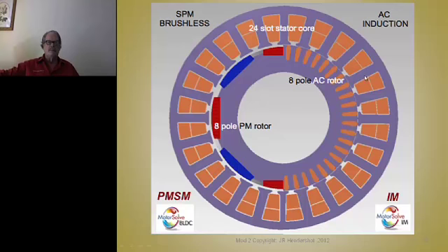But remember I told you how the stator field rotates at 60 hertz or whatever frequency, but the rotor has to slip. It has to rotate less than that. So if these 4 bars are creating a north pole, and this rotor is going slower than its synchronous speed, then that means I got to drop a bar and add a bar as this rotates.